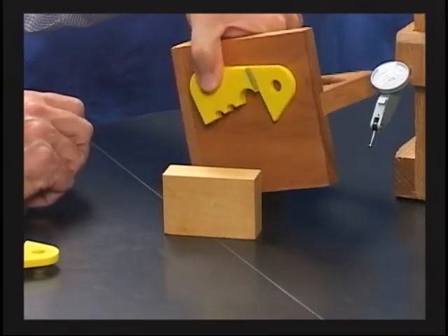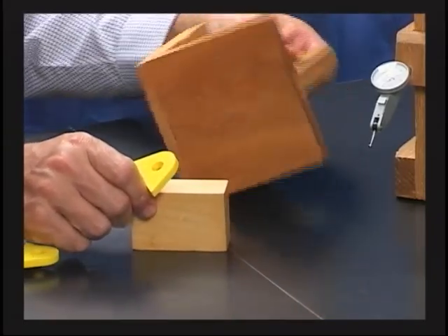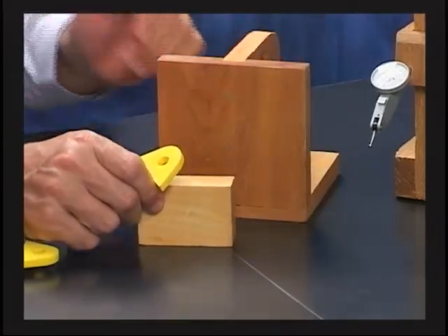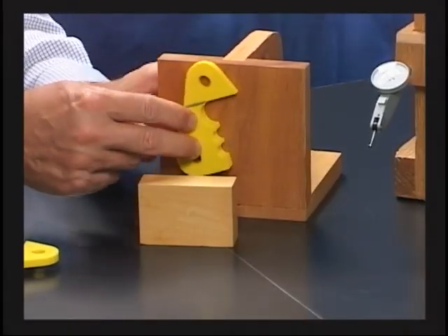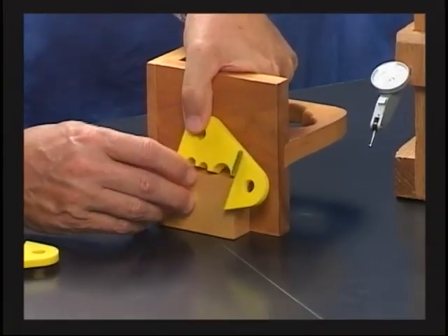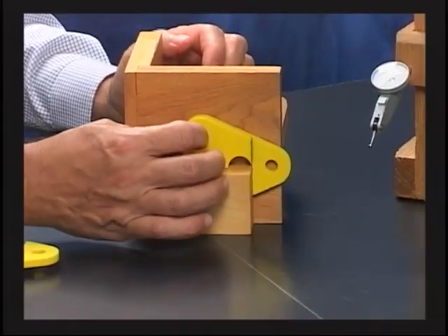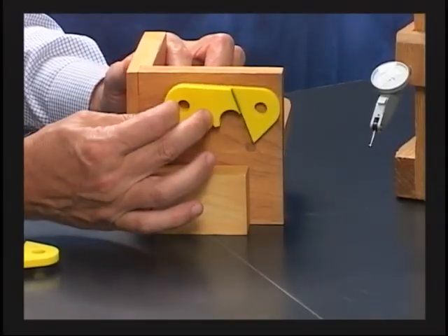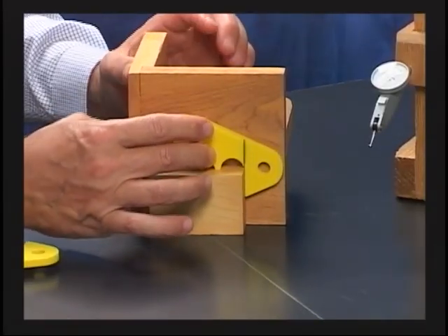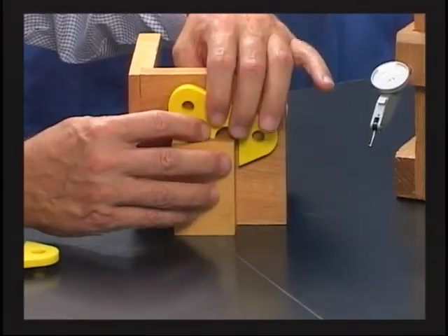I might take the angle plate. Remember how this angle plate is 90 degrees. Any way you turn it, 90 degrees. We know it's calibrated on a periodic basis. We know that it's good. So I might take this part, turn it sideways here, bring it down to this top surface. It's lined up on the gauge block now. You notice that basically on this one, it's a simple one. I have primary datum, and I'm bringing it down to my secondary datum. It's locked on. And what I'll do is I'll raise mine up here a little bit.